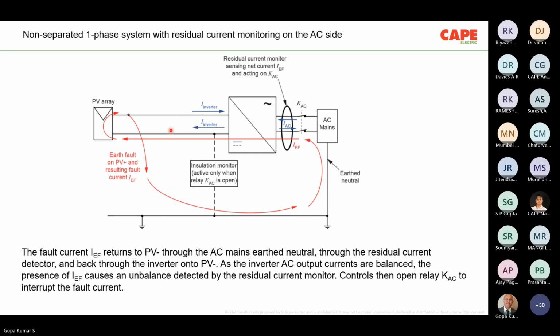Now, every day, the device, the insulation monitor, for example, every day the inverter before starting the operation is supposed to check whether the insulation resistance is in place or not. Now the challenge. So whatever these three examples which I have shown, like this, we can define several examples. These mandatory requirements, for example, measuring the residual current, operating the relay, daily basis monitoring the insulation resistance. These are mandatory safety requirements.